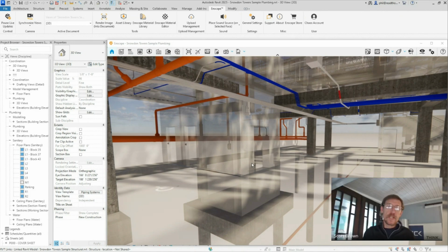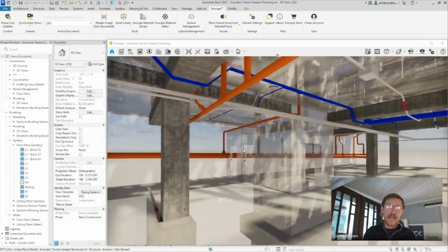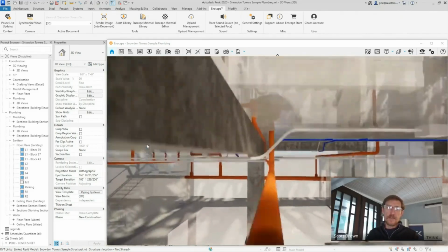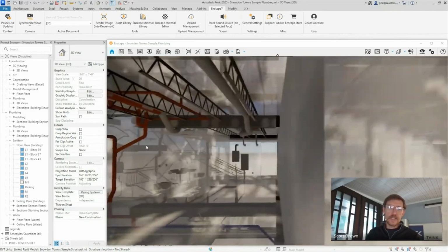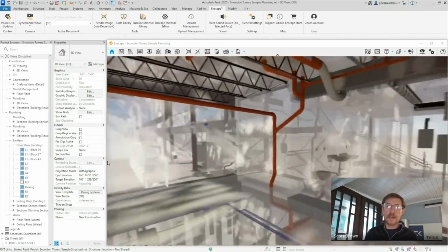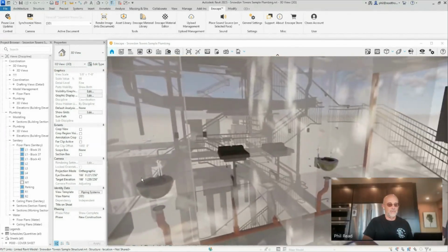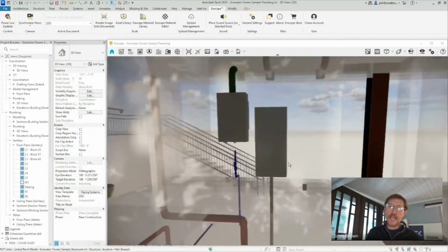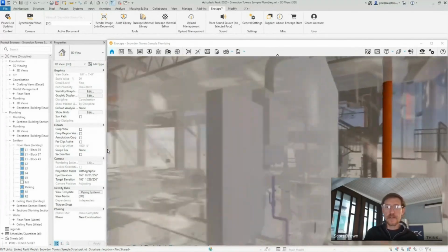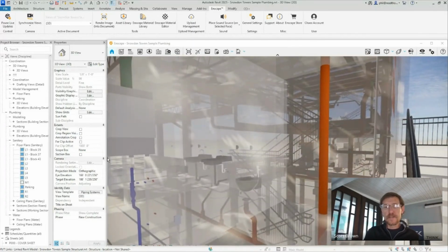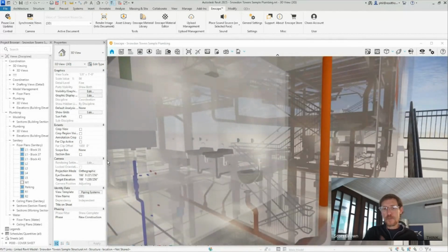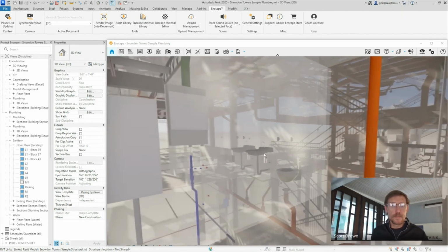Right. So we do this whole model audit process, and I take a snapshot, but Craig and I were playing with this last night. You have this issues tool in there, and it'll save the snapshot right within Enscape. Within the issue. Yeah, and then you can save that out, export it, and load it back in later. So you could use it to track these issues right here. I'm not talking about the BIM issues plugin. There's the communication one, that little comments button next to your house.